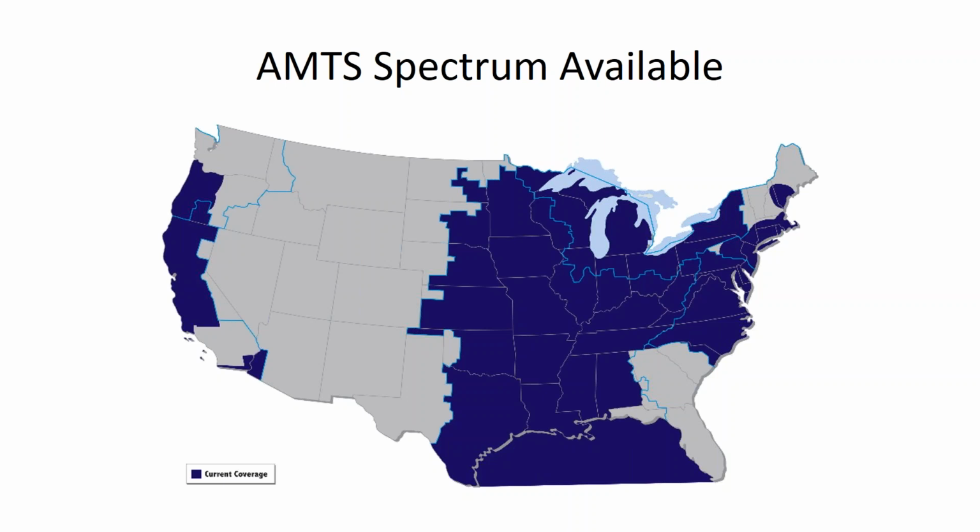If you look at the New Jersey, New York area, for example, where we have some incumbent licenses, we operate and are protected at a 20 dBu interference contour. The co-channel license holder's 38 dBu service contour cannot come into the 20 dBu interference contour.